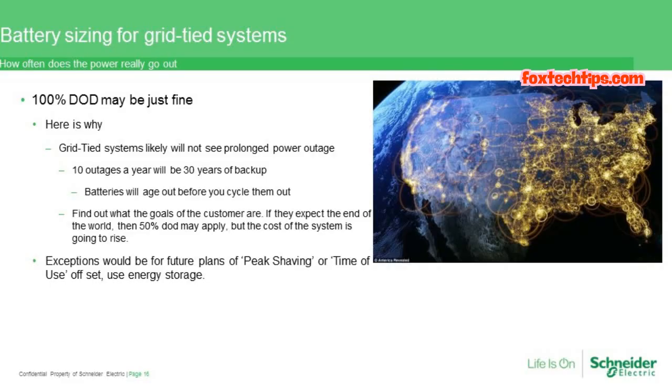When we talk about which product from Schneider, if it's the Conext SW or the XW Plus, then we have to look at when we're going to be using it. One thing to note is that the Conext SW is not a grid tie inverter, but is a really nice inverter for, say, a small system of 3 to 4 kW of solar, and you need to AC couple to that. So that's really where the SW shines, and cost per watt is very, very reasonable. With the XW Plus, of course, you can do the whole AC coupling or do grid tie with battery backup from the very beginning. And again, this makes the most sense.